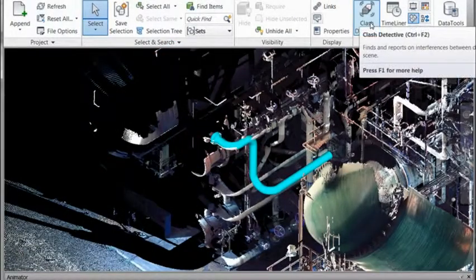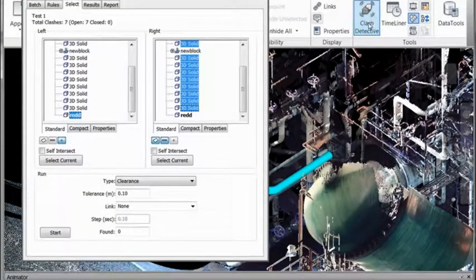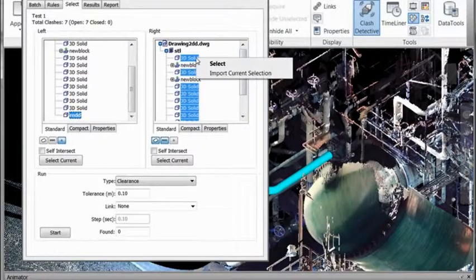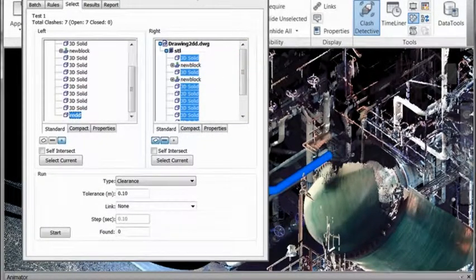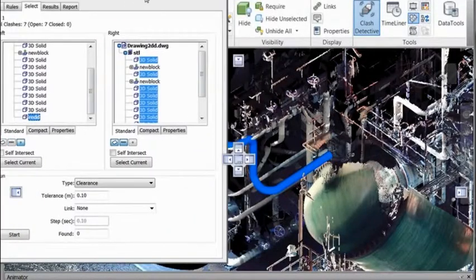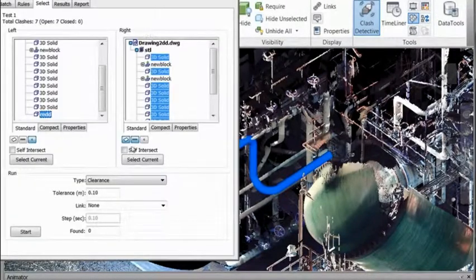Finally, clash detection for revamp projects is very important, but can be extremely difficult since not all of the plant is modeled. Autodesk Navisworks Manage supports point clouds, so clash detection can be performed to check new piping as modeled in Plant 3D. With the existing plant represented by point clouds, there is no need to convert the clouds.